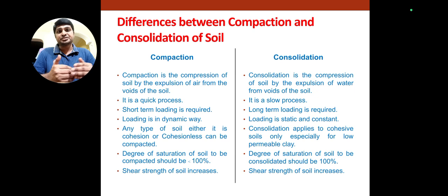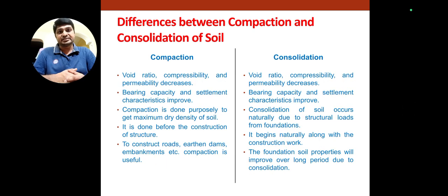The shear strength of the soil increases in both ways, either in compaction or consolidation. Void ratio, compressibility and permeability decrease in compaction, and also in consolidation. The bearing capacity and settlement characteristics of the soils improve in both ways.